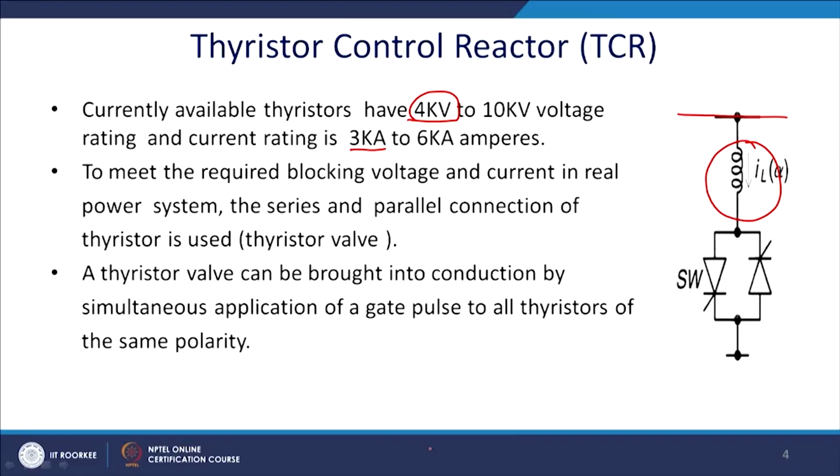A thyristor valve can be brought into conduction by simultaneous application of gate pulses to all the thyristors of the same polarity. There is a factor of safety here.